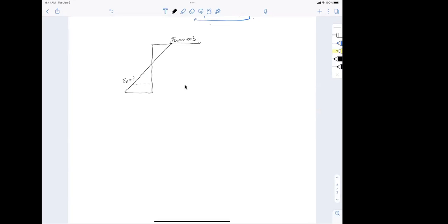In other words, at failure, has the steel yielded or not? Why is that so important? Think of it: say your strain in the steel is lower than 0.002, let's just do something extreme. That means your steel is elastic. So in terms of the stress strain curve for the steel, you're somewhere here. That means that when your concrete is bending and failing, before it reaches failure you don't see anything on the surface. There's no cracking, because the deformation is still so small.